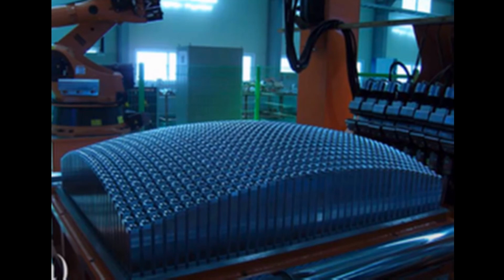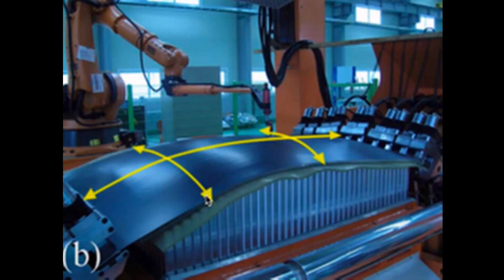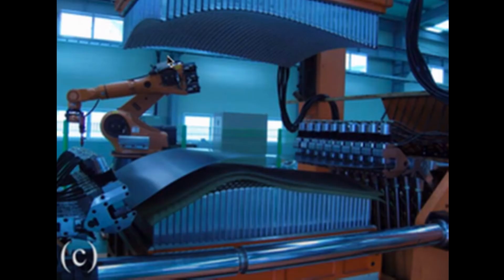So the method chosen during DDP construction is multi-point stretch forming. There was an existing multi-point forming method. This method was to make several posts into desired molds and then press metal plates on them. However, this method left round post marks on the panel itself and did not produce a clean finish surface. Therefore, DDP used stretch instead of press by placing rubber plates on top of conventional multi-point forming.